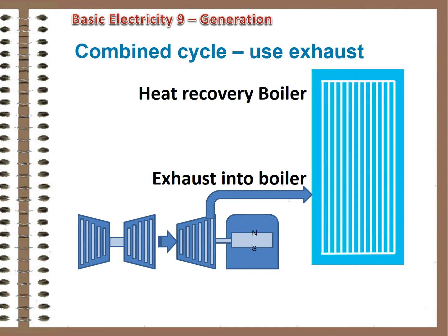But they can be made a part of what are called combined cycle units, where they are used as the heat source to a steam boiler. In this type of unit, the gas turbine takes the place of the fans in a typical boiler. The exhaust from a gas turbine runs about 1500 degrees Fahrenheit, over 800 degrees Celsius, so if it is directed into a boiler designed for it, sometimes with just a bit of supplemental firing, it can boil water and make steam to drive a turbine.